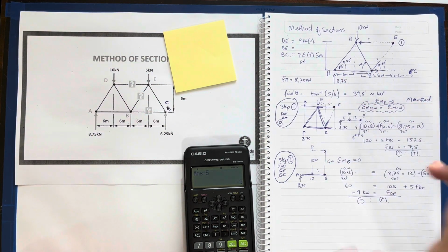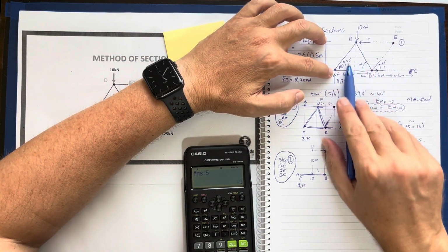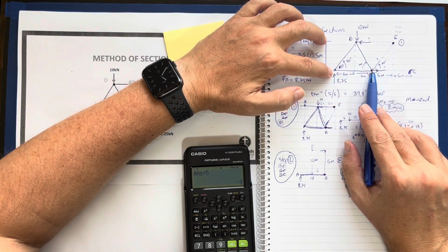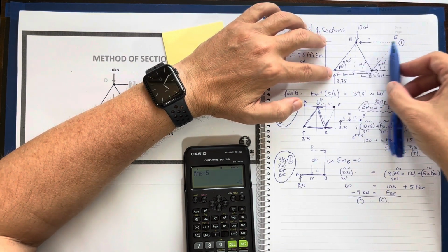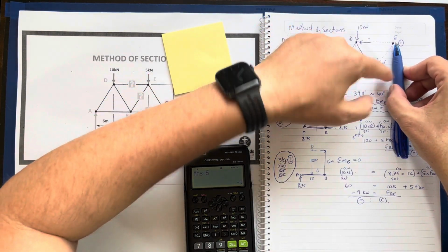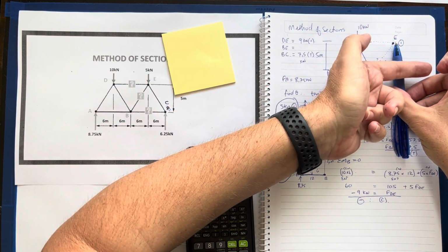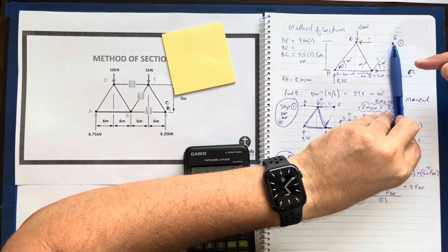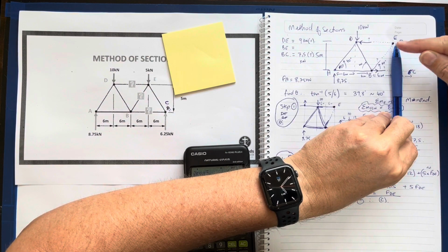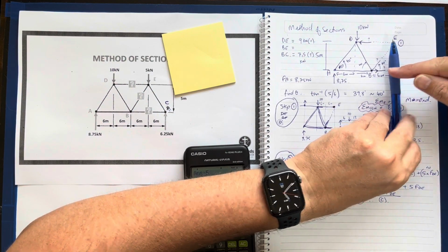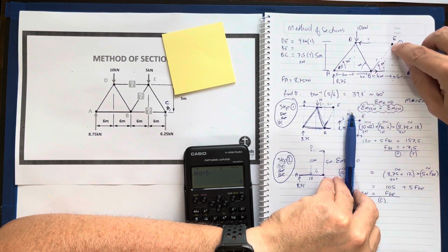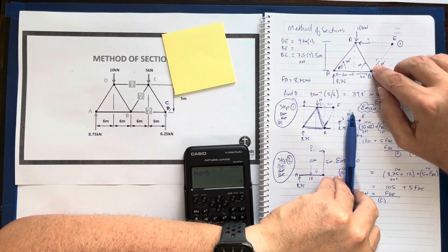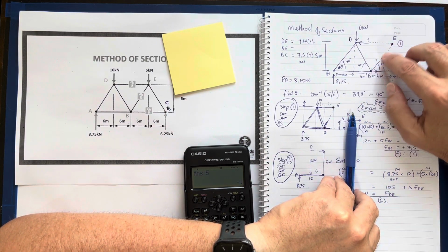The reason why I need to go to A and not, let's say, to D or anywhere else is because all of my forces, at the points I've been working with, have effectively been at 90 degrees to a beam that I can place there and there as well. This particular member is actually axial, at an angle.